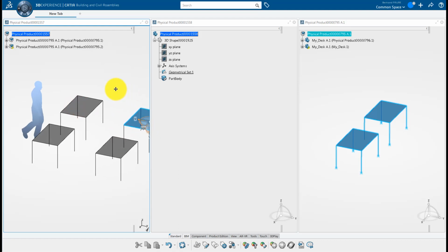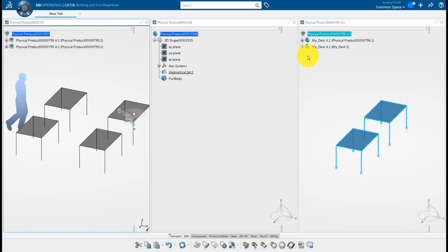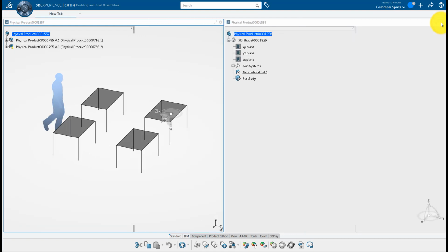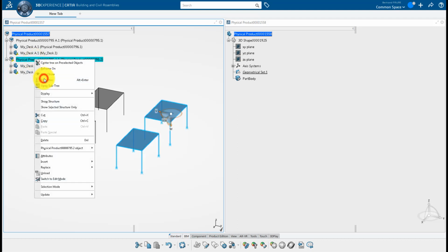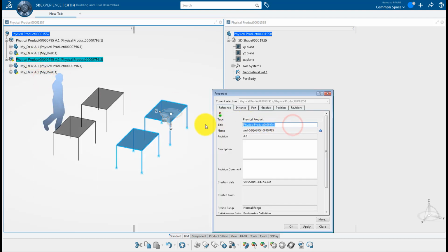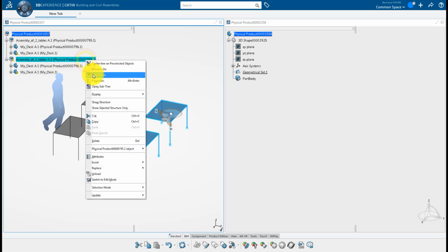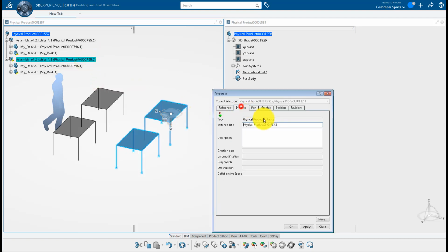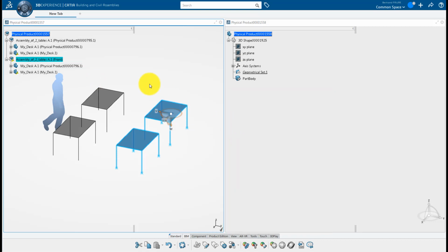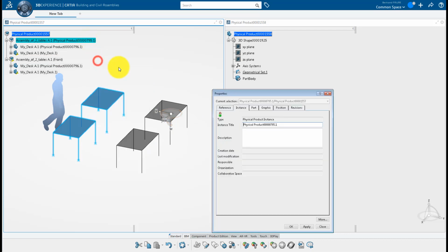You can close the widget containing the reference of product with 2 tables, as this model is already loaded in session. You can change attributes from there. For example, the reference title of this product is changed simultaneously on both instances. You can change the instance title, which is specific to this instance of the product, under its parent. So you can use it to describe the location, for example. Edit the second instance title to complete the location description on the first instance.